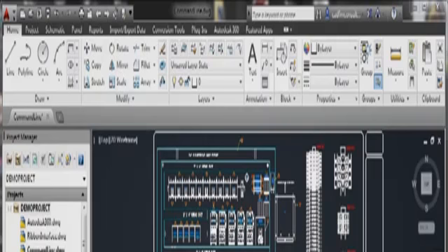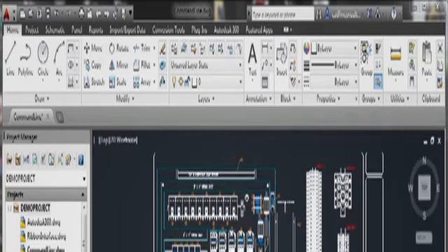For those of you used to the older versions of AutoCAD where the command line is actually locked to the bottom of the AutoCAD screen, you'll see the command line down here at the bottom of the screen now is movable. Click on the little grey area there on the left and drag, and you'll see the screen update. So as I move now, I can park the screen wherever I want to. You'll notice as well it is transparent. You can set these transparency settings in here where you customize it.